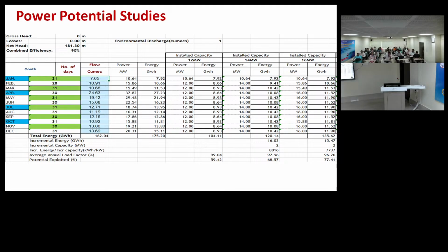At least provide some cushion. Exactly, it should not be equal; at least provide some cushion so that we can have some intake structure in this portion. That is why some 10-15 meters cushion we should always give. So that will be our MDDL. MDDL we have fixed. Then how to fix FRL is different.